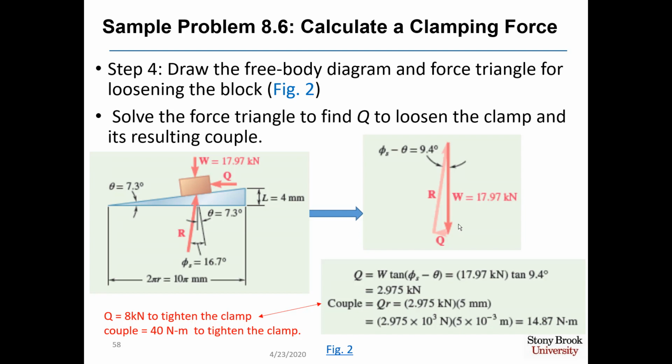When you use a jack screw, that's the one thing you notice when you're doing your engineering thinking as you sweat out there in the sun changing a flat tire: it takes a lot more effort to lift the jack up and get your car up in the air than it does to turn the screw the other way and let the car back down. Which is nice, that at least after you're tired and frustrated and you finally got your spare tire changed out, you don't have to put as much effort in order to finish the job and get the car back on the ground.